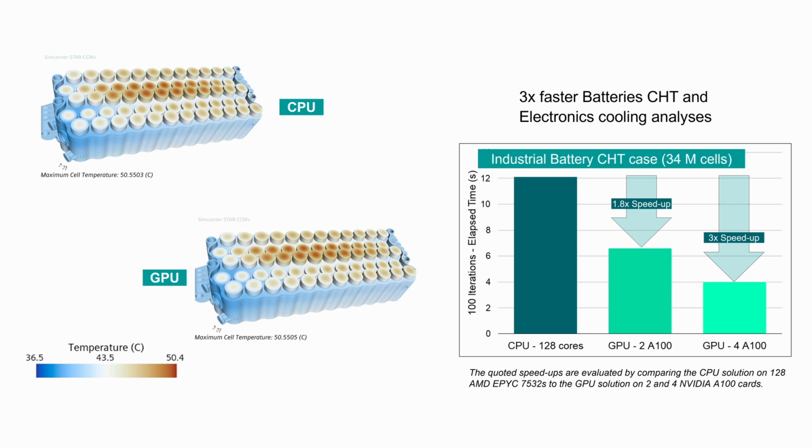If we think about the sliding mesh, then I did allude to wheel rotation. So really having this sliding mesh functionality on GPU allows you to do full unsteady transient automotive aerodynamics. So effectively that's the full vehicle transient in time with the wheel rotation explicitly modeled, which again is quite important for accurate prediction of the drag.